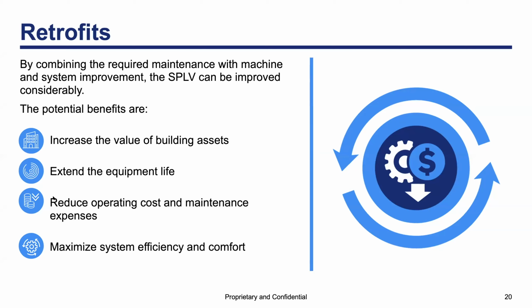From the operational standpoint, we need to consider three important factors to achieve energy balance and maximize this efficiency. Number one, we must eliminate the energy that is not used. A perfect example of this energy that is not used is a throttling valve, like a triple duty valve on a pump.